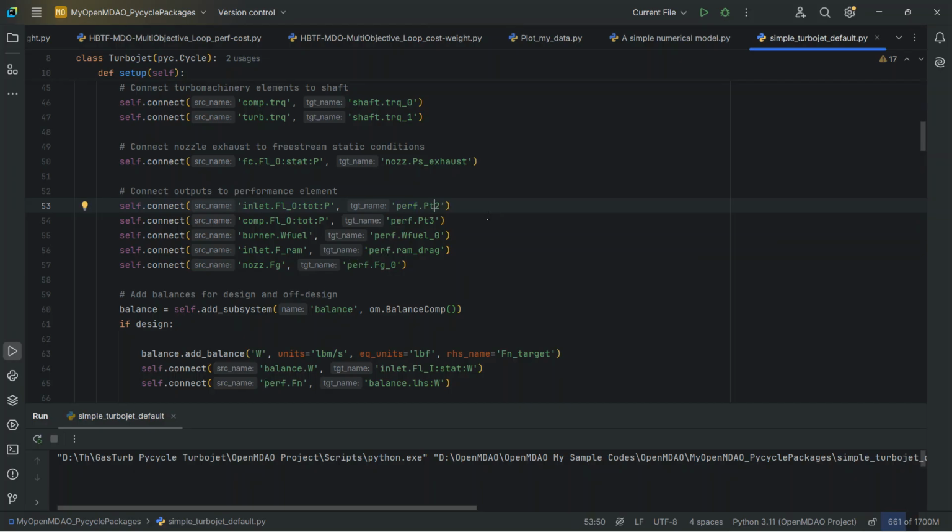Point 2 is going to be the point that has the lowest pressure, okay? And then the compressor's output total pressure is going to be the performance's total pressure 0.3, and dividing these together will give us the OPR of the engine. So it's going to need these two, the lowest pressure and the highest pressure of the engine, to calculate the OPR, right?